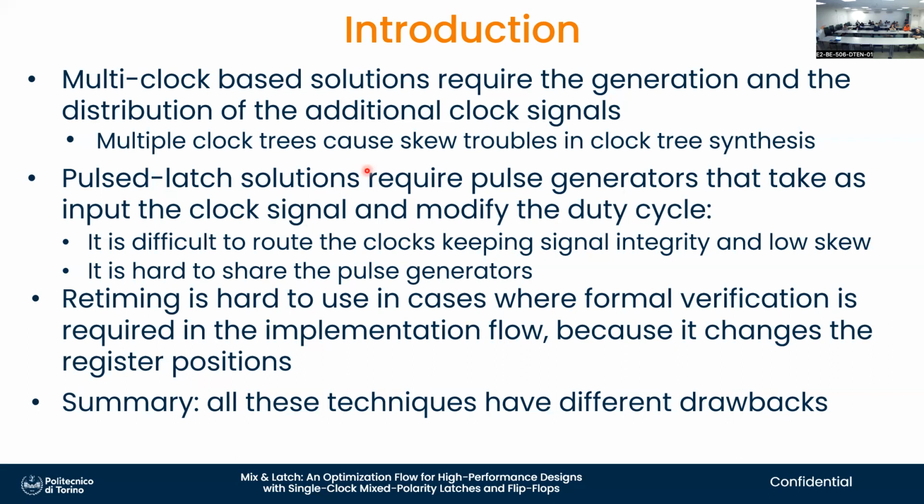If you have a flip-flop at the output of an AND gate, you can move it before the AND gate and it becomes two flip-flops. Logically, same functionality, timing is different. You have, in effect, borrowed some time, to use the terminology that I used earlier, from the input to the output. You have moved some delay, some complexity from the previous stage to the next stage, and you can do vice versa.